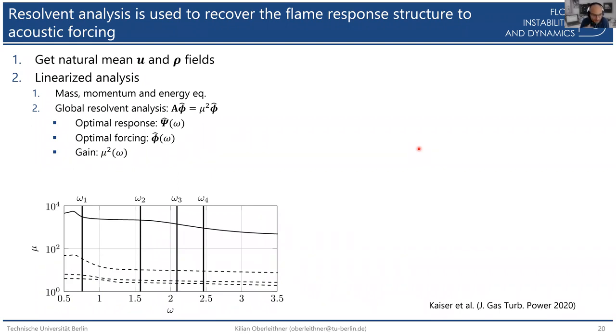So we get a very pronounced low rank characteristic. So the gain of the leading mode is much larger than all the other modes. So that is nice. And it also tells you already that there seems to be a hydrodynamic instability that dominates the response. So this is the Kelvin-Helmholtz type instability.